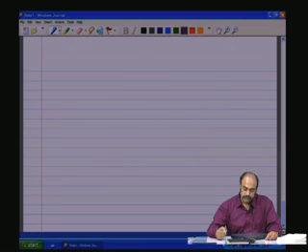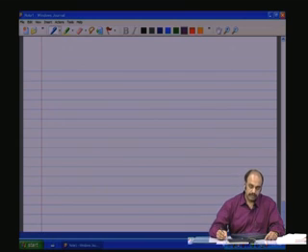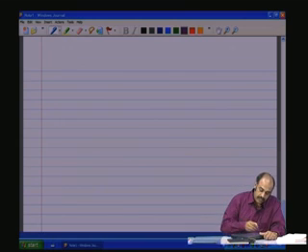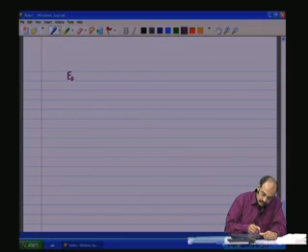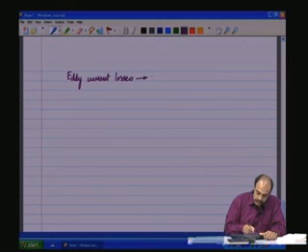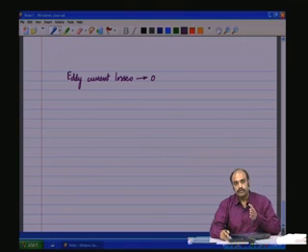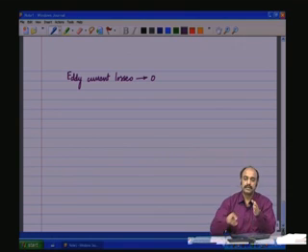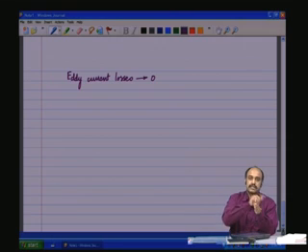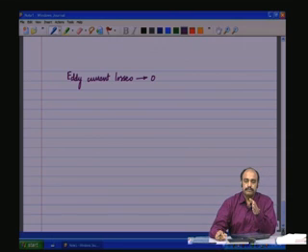One more feature that is expected of the ideal transformer is that there should not be eddy current losses. Losses should also tend to 0, which means the resistivity of the core material, because if there is a flux flowing in the core material, there is going to be currents around the flow of the flux in an orthogonal plane.